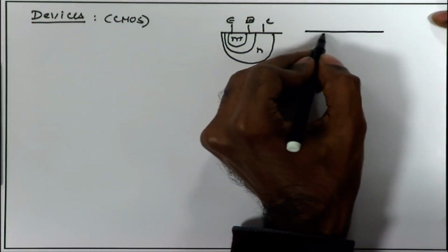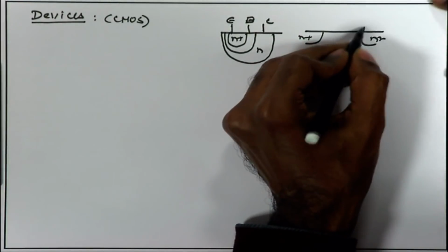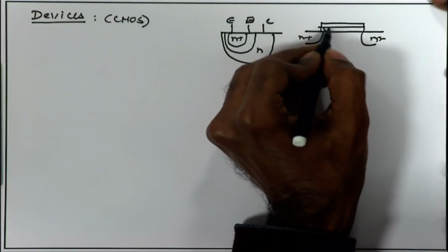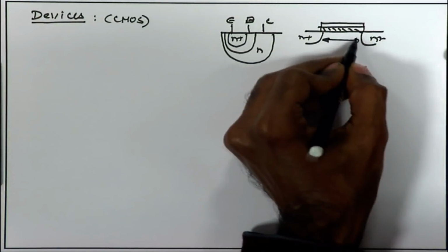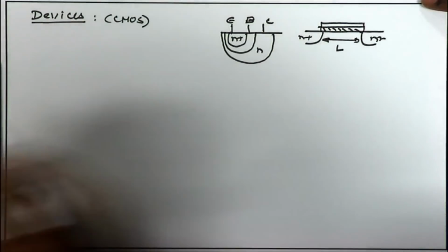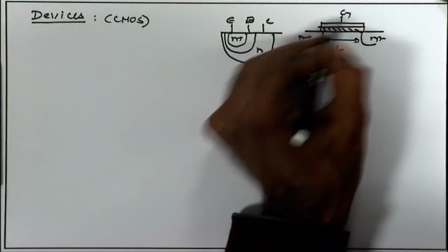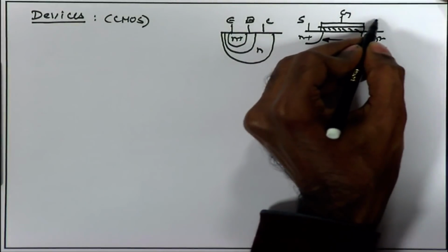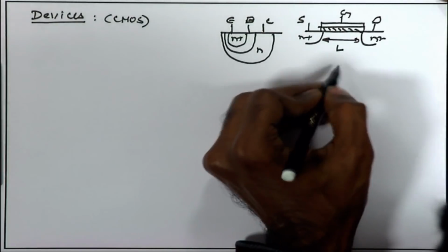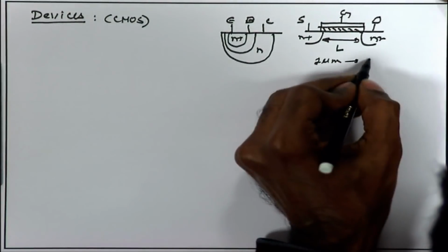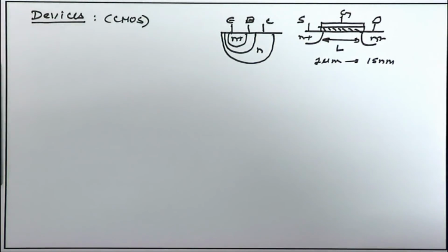As compared to that, the MOSFET is a lateral or relatively 2D structure, which has been much more convenient to scale, and the industry has been very diligently following Moore's law and has been able to scale the channel length of the MOSFET starting from the earlier days of 1 micrometer going down all the way to 15 nanometer, and today they are progressing towards 10 and 7 nanometer.